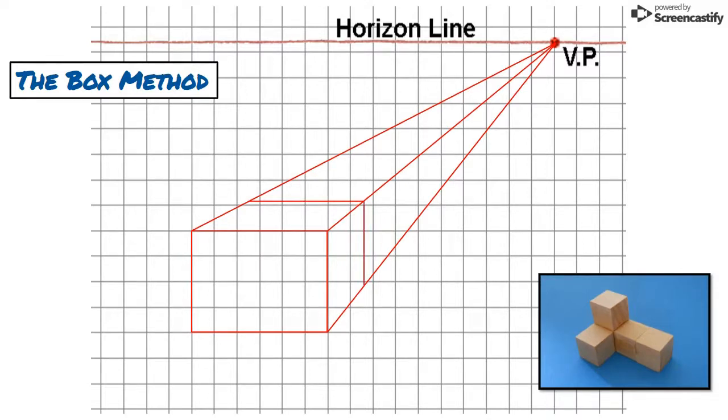With the box complete, locate points and construction lines to identify corners and edges of the object on the surface of the box. Then use object lines to trace over the edges of the object on the visible surface of the box.